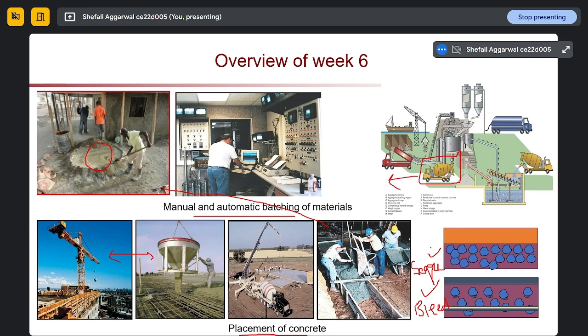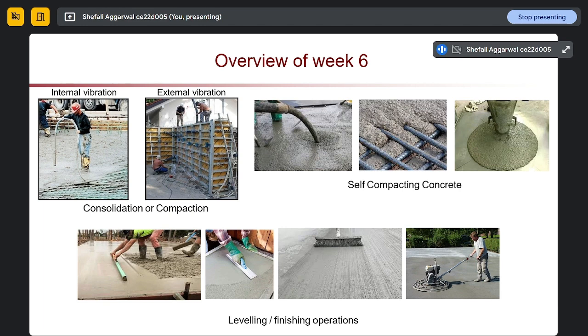And if we talk about normal cement composition, as we have seen in the previous slide, we have sources of calcium, silicon, aluminium, and iron. So mainly oxides of these four materials will be available in bulk. Other than this, we have some minor oxides like magnesium, sulfate, sodium, and potassium. So these are the normal oxide composition of our cement.